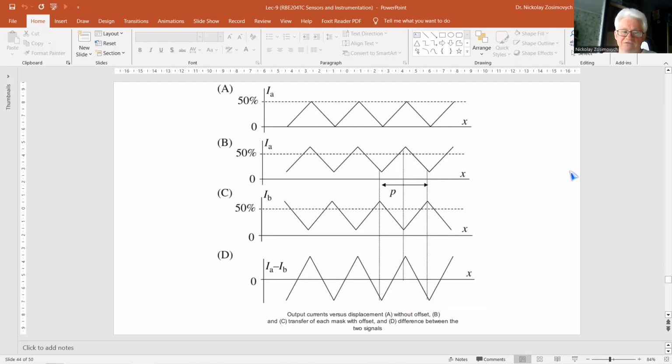When the relation between displacement and output is known, this information can be used to find intermediate positions between the maximum and minimum values of the triangle. And hence, the incremental encoder offers the possibility to interpolate between successive slots, increasing substantially the resolution of the sample.